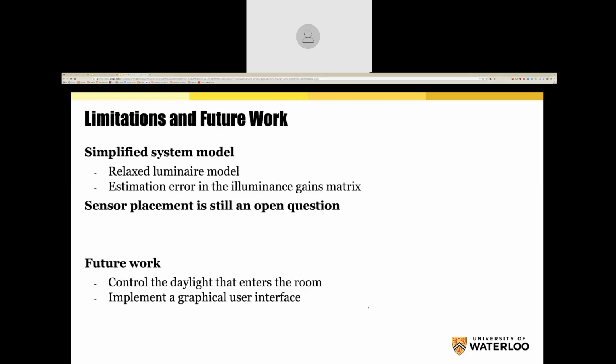The distinction between the two actually has to do with system memory. So with an HVAC system, when you turn on the cooling, it takes anywhere from 5 minutes to half an hour for you to have the impact that you want. So there's a considerable amount of inertia in the system, right? With light, there's zero inertia. It's beautiful. You turn the light on, there's no memory. It's very, very instantly controllable. So all the math becomes much, much easier. Whereas for any kind of HVAC system, these transients, especially if you're talking about chillers, air handling units, VAV control boxes, etc., it becomes really, really complicated. So lighting is much nicer that way.